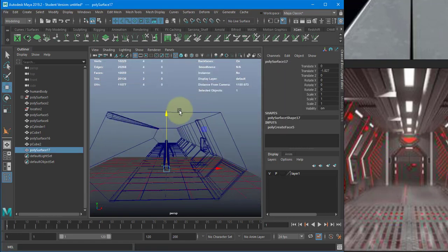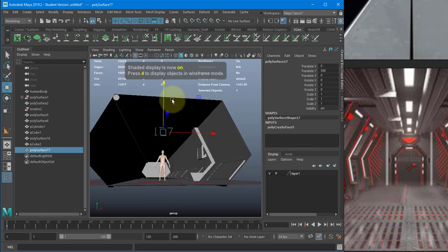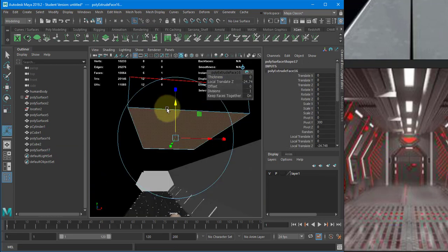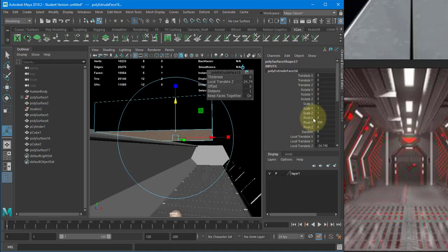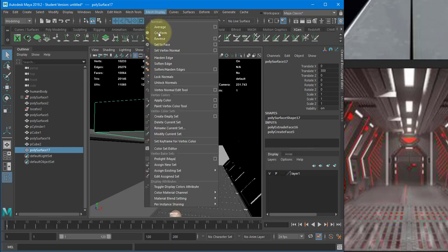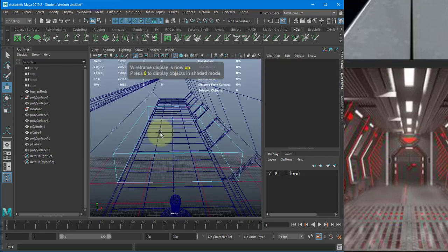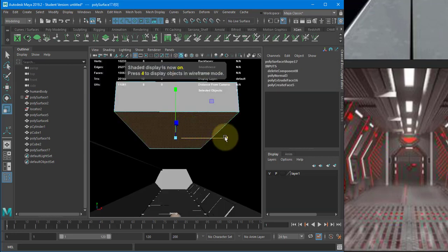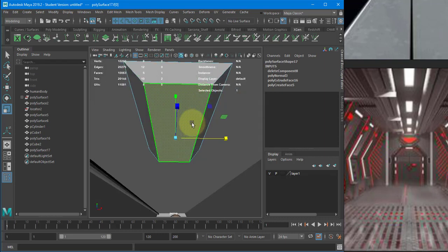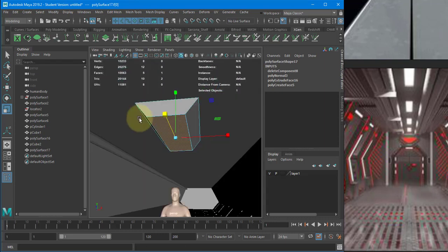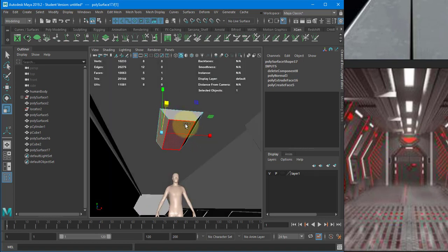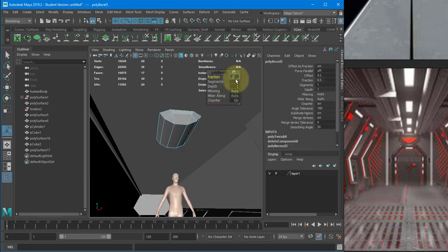All right. So there's my light that I'm going to use. I'm just going to extrude this. And negative 25. And then reverse this. I'm going to delete this top face because I don't need that. And then I can just kind of scale this in like this. I could scale like that, but I think like this looks good. I think that's going to be cool that way. And then bevels around. Too much. 0.2, 0.1. All right, that should be good.